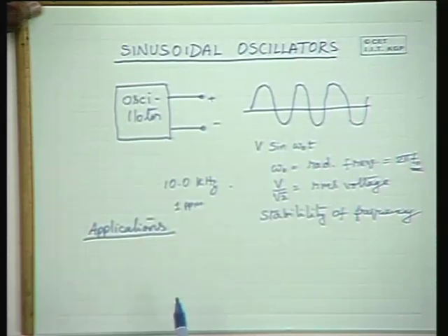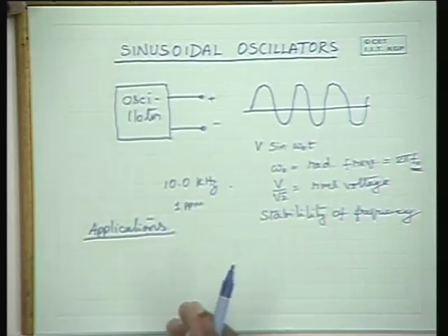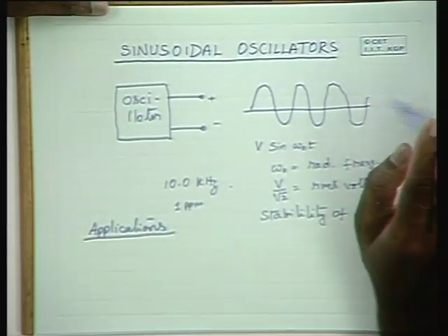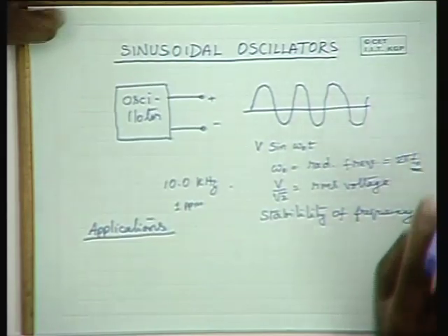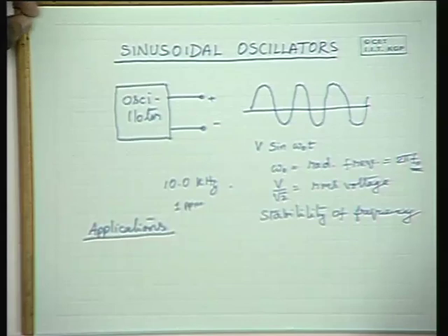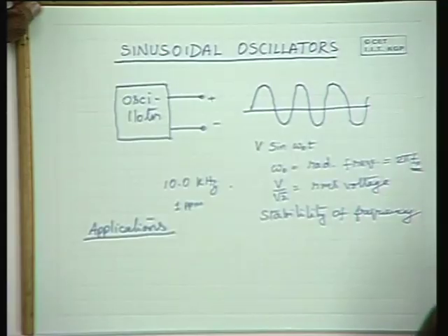So, there are many applications, and as an example let me take the wall clocks and the watches. You have a stable quartz oscillator inside a watch. Why do you need that? If you do not use a highly stable oscillator, and if its instability is 1 ppm, please note that for every 1 million seconds there may be 1 second error.